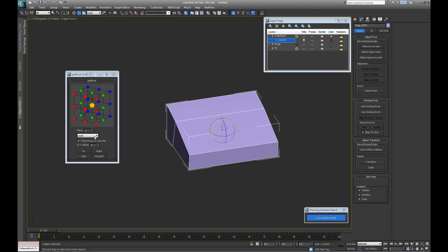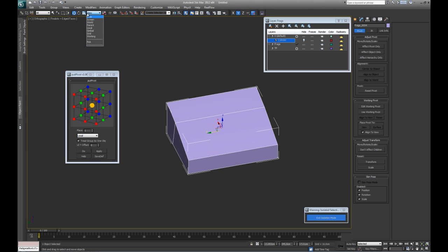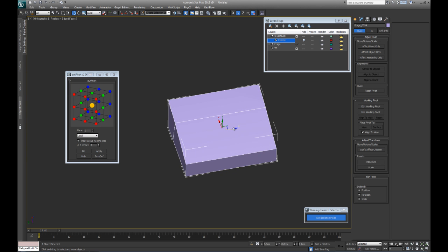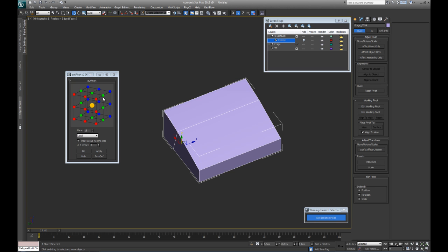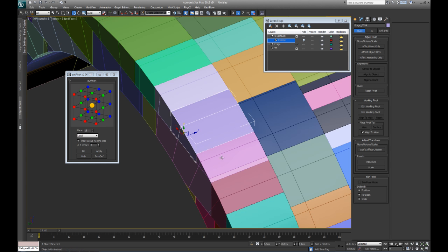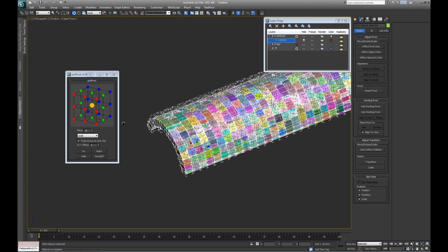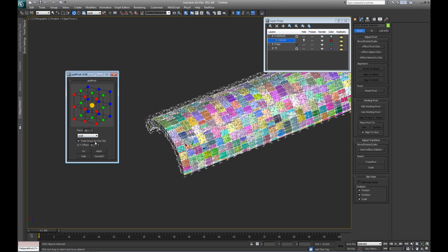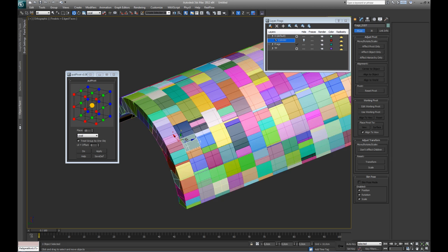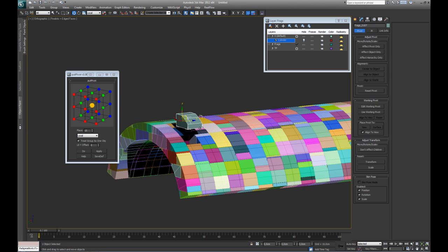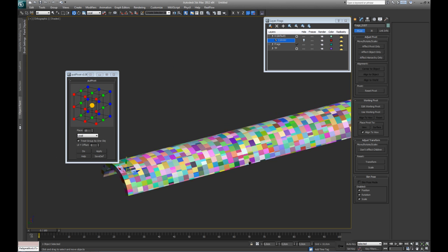So we're gonna use the put pivot, and if you take and put local, you will see that the Z axis is downwards. So it should be this. Yeah. You can click the small dots to place it, and you might have to try a few times before you get it right. However, this seems to be the right one for this, so I'm just gonna exit my isolation, select all my fragments, and press this button. As you can see now, the pivot point for all my fragments has been placed correctly. I'm just gonna take off shaded, or else this might not be as smooth as I want it to be.